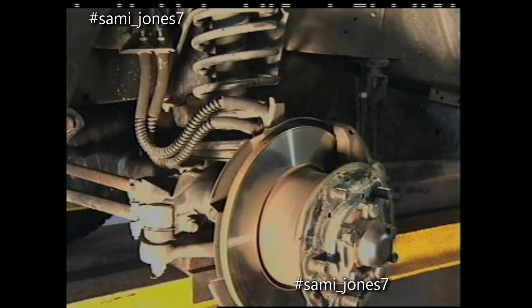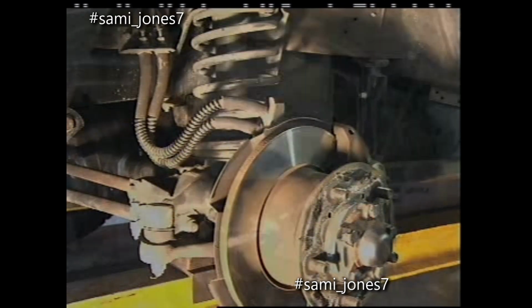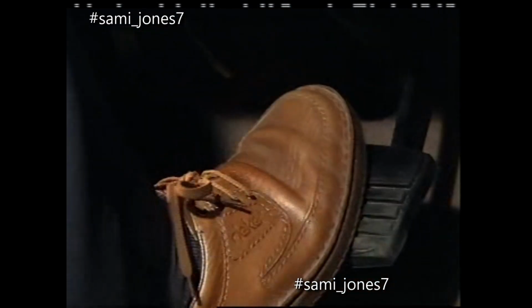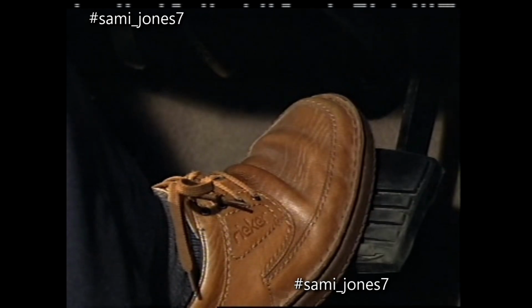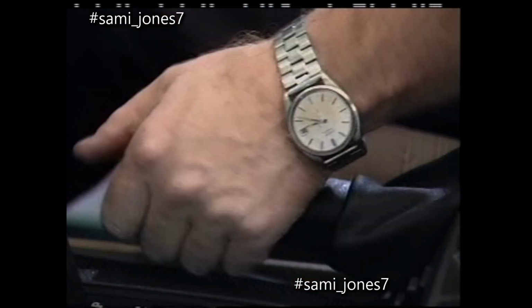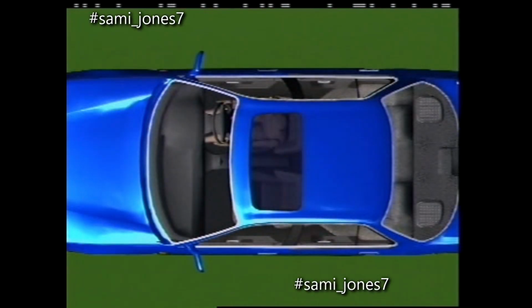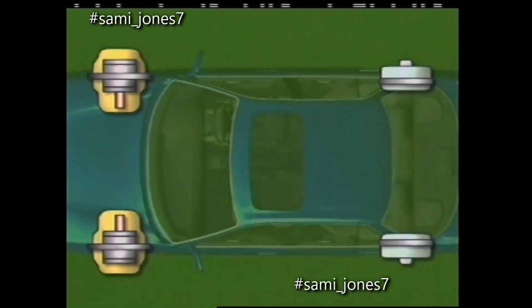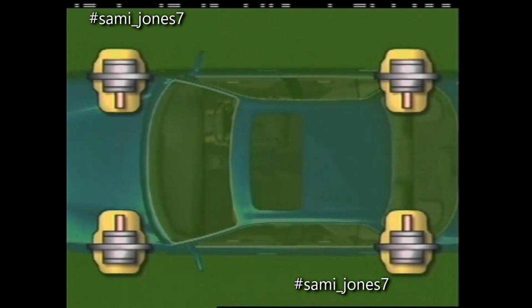A basic hydraulic braking system has two main sections: the brake assemblies at the wheels and the hydraulic system that applies them. There is a brake for when the vehicle is in motion, usually a foot brake, and a park brake for when it's stationary, usually operated by hand. Some systems have all drum brakes. Some have disc brakes on the front wheels and drum brakes on the rear. Others have all disc brakes.